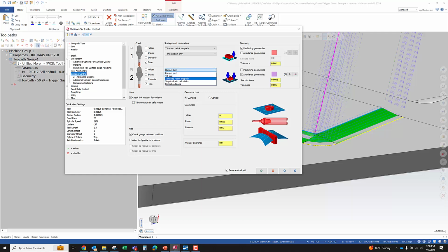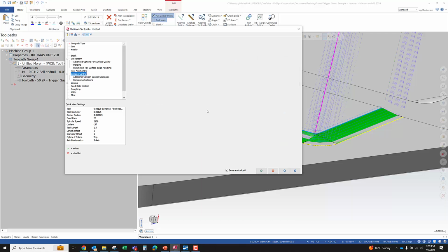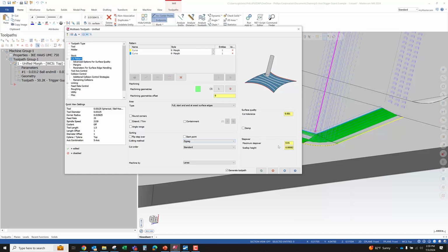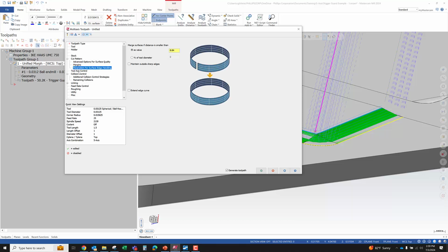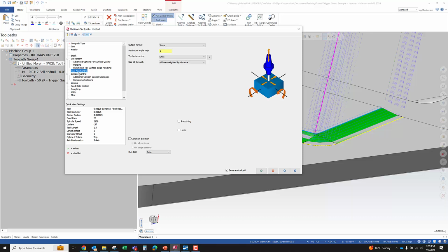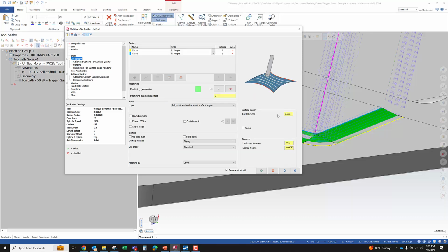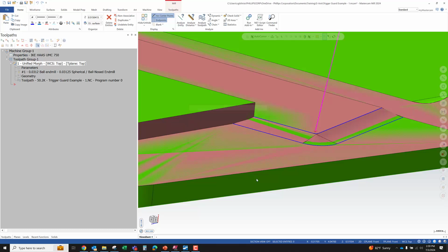We can also say trim and relink, trim collision only from the avoidance geometry. If we do that, we want to make sure that we have enough points being output. I think a 1 thou tolerance should be okay. So if I just tell it to trim and relink, instead of retracting away from that normal axis, because we are tilted, that's the other thing we have to consider.